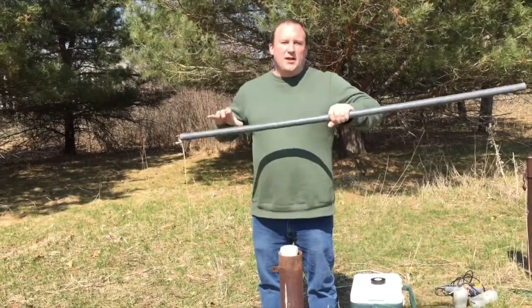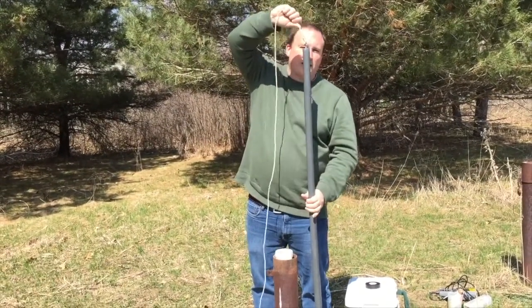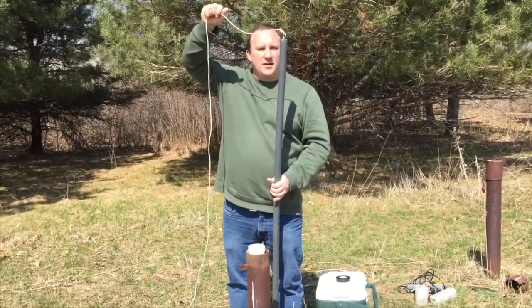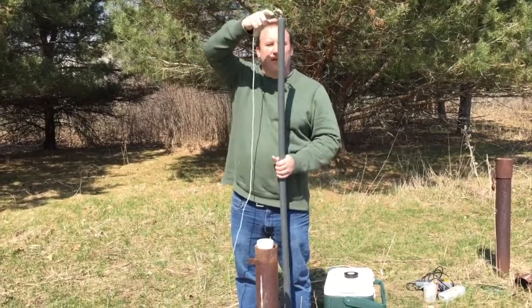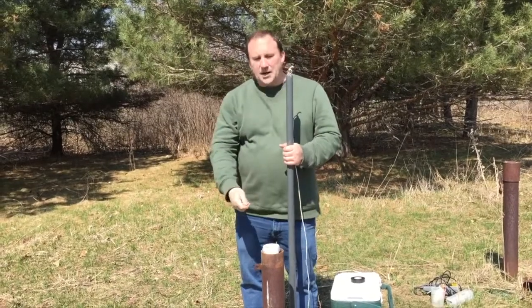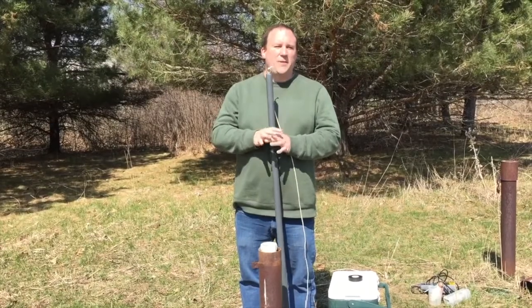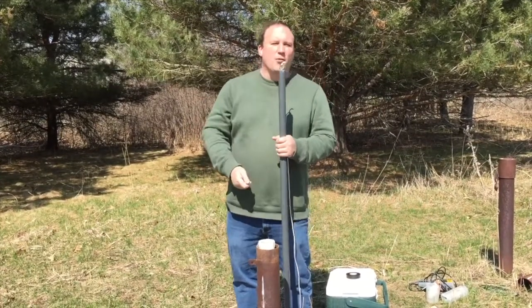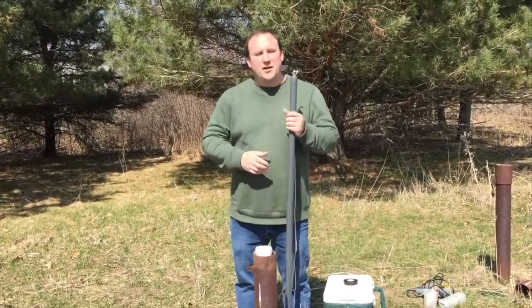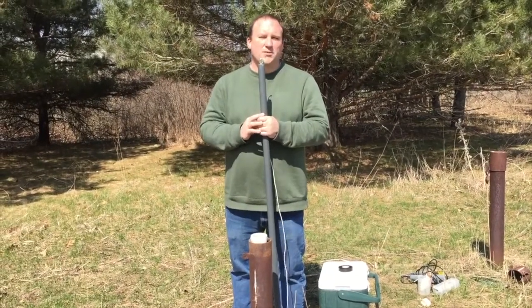before I do this, I need to know exactly where to put this slug. So what I want to do is get it ready so that it's right above the water table, and then when I'm ready to start my experiment with the data logger, it's going to go down below the water table. I'm going to leave it sit there, tie it up here for a while, and then wait for whatever response to dissipate. We can gather enough data, and then we'll pull the slug out after it's equilibrated. So I'm not sure how this is going to work. I've never done a slug test on this well before. I anticipate that it will probably take 20 minutes or so to equilibrate.